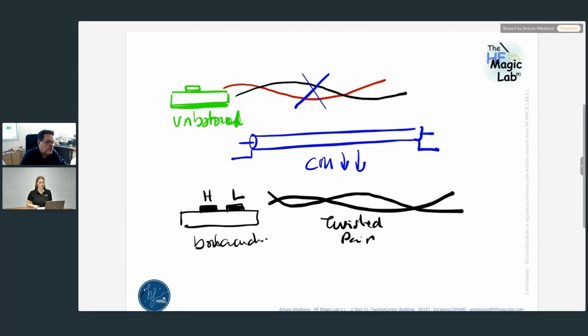If you are not able to do this, the only possibility to minimize common mode is to introduce common mode chokes or to make some kind of filtering with common mode capacitors. I mean, you will need some kind of capacitor from each line to the ground plane that you have, like the return path. Sometimes this is impossible because this return path is not accessible.